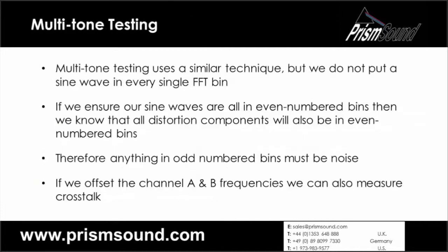Okay, so the other one, multi-tone testing, uses a similar technique of very accurately placed sine waves, but this time we don't put one in every single FFT bin. What we do is we make sure, firstly, that all our sine waves are in even numbered bins. And what this means is that we know any distortion components will also be in even numbered bins, because they'll be integer multiples of our fundamentals.